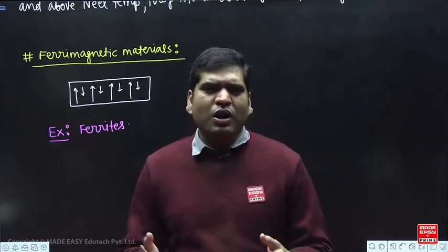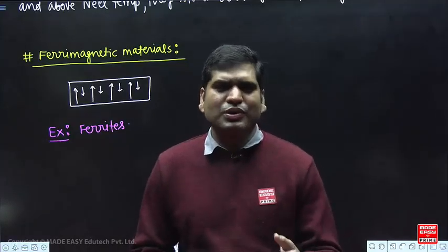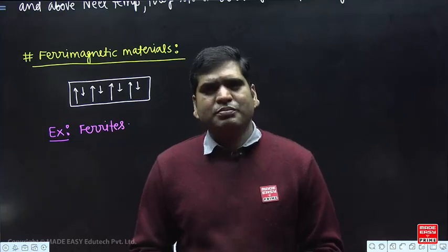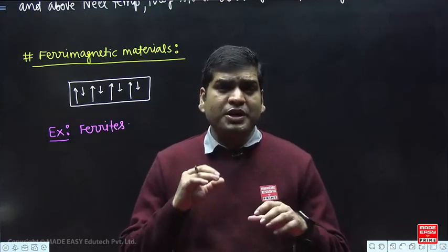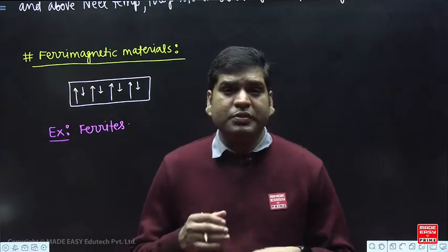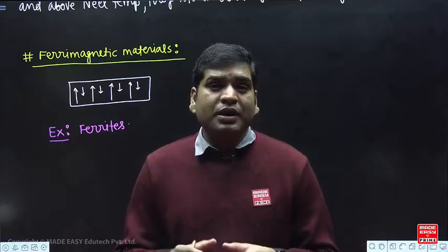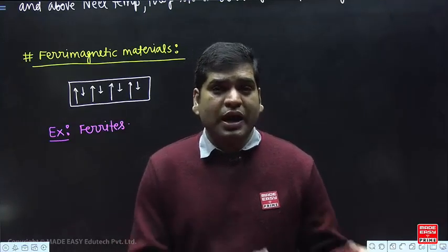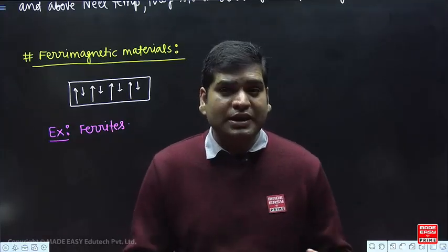Someone will say, why only at high frequency? We can reduce the loss at low frequency also, so let us use them at low frequency. The reason is they are ionic materials. So ionic materials are brittle materials. It is very difficult to shape them, and if it is difficult to shape them, it means their cost of production will become very high. So they become very expensive. That is the reason why we do not use them at low frequencies. But at high frequencies, we are not left with any choices.